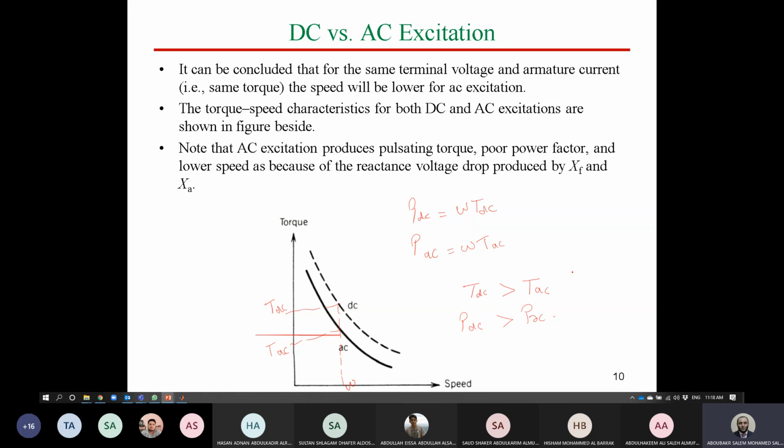To be honest with you, we discussed previously, guys, that the universal motor exists a lot in our home appliances. However, in most home appliances, there is no internal AC to DC converter in order to convert the AC supply to DC. This is because all companies try to produce home appliances at a competitive price, okay? And if you include a power electronic converter, it will need some digital controllers and programs and so on, and it will increase the cost. And this is not suitable for home appliances applications.